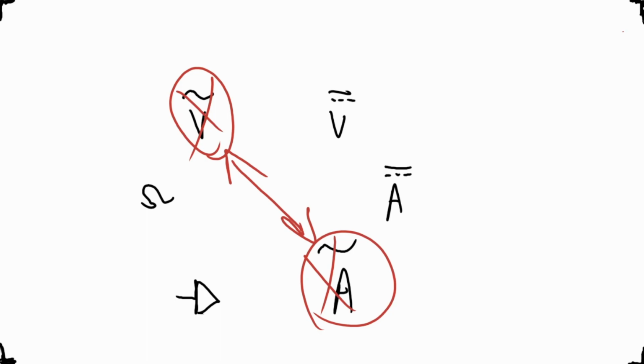If you're asked to measure the voltage, specifically measure the voltage with this, the V, where it has this symbol here, the two lines. This indicates direct current, DC. We're using a DC circuit, so you want to measure voltage in DC. Again, if you're asked to measure current, you're going to be measuring with amps, which is in DC as well.